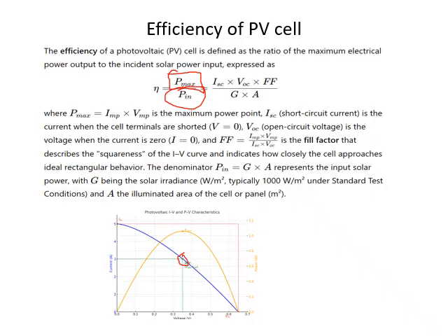But the overall solar irradiation is coming in watt per meter square. Remember, we have learned about this. Solar radiation is watt per meter square. So I need to involve the area for which I have the solar panel installed. So the solar panel's area will be one factor, because I am using the solar irradiation in watt per meter square. Multiplied by area in meter square, it will give me only watt, the incoming solar irradiation, and how much of it is converted to the power that I require will be IMP times VMP.